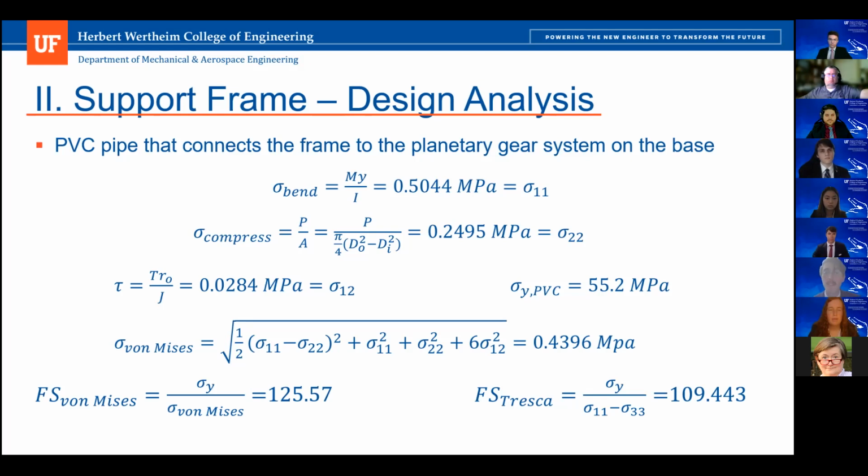The part was then evaluated under von Mises and Tresca's failure criterion, with the PVC far surpassing the necessary factor of safety of 2, with both greater than 100.